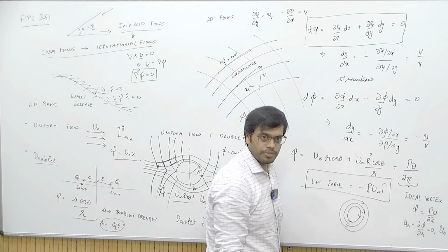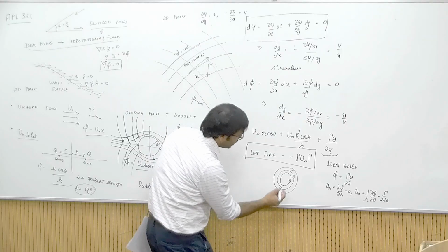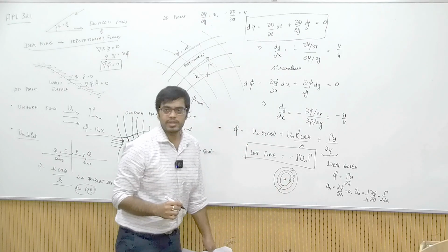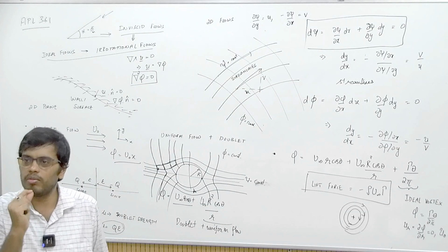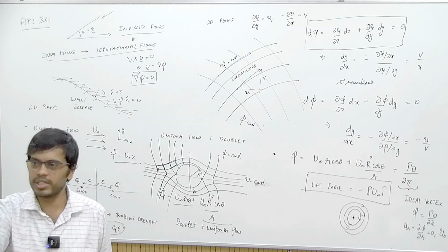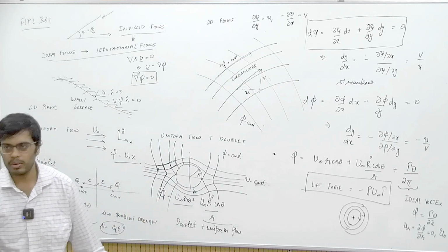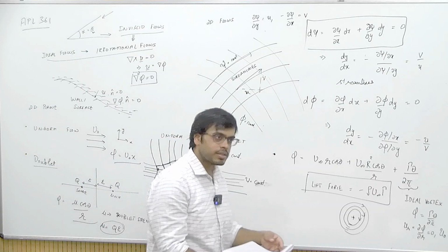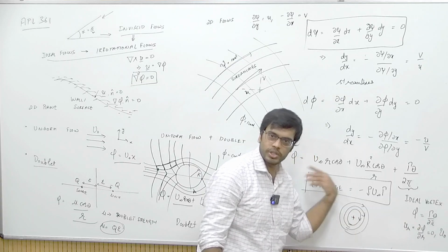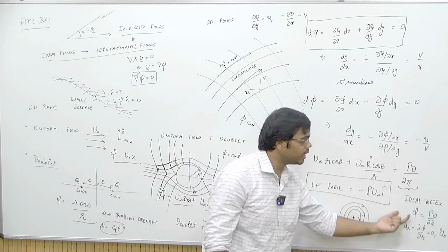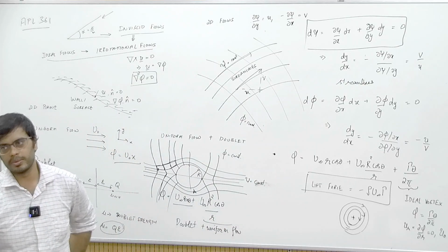Okay. You have these tangential velocity profiles, but if you compute the vorticity, it will be 0 except for a point, which is the center of this ideal vortex. So, an ideal vortex is like a concentration of vorticity at one point. At that point, your vorticity tends to infinity, and at all other points your vorticity is 0, which is why we call it an ideal vortex. The flow is rotational except for a point. The flow is rotational throughout the space except for a point, and it is a vortical motion, but the vorticity is 0.